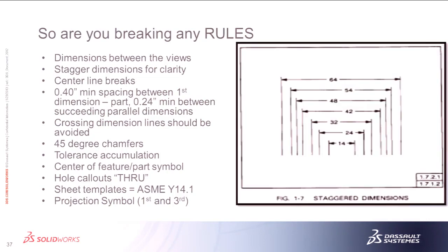The next one is stagger dimensions for clarity. This is right out of the standard. The picture is you should stagger them when you have a whole bunch of them, just like it's shown there, so people kind of read it better.